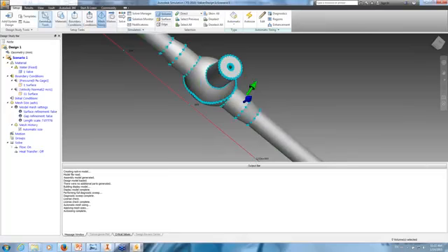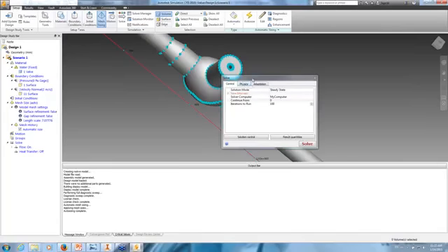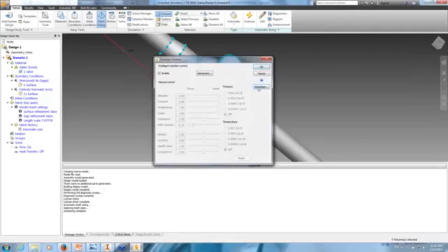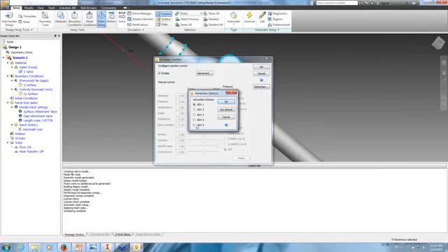So we did the material, the boundary conditions, the mesh, and next I'm going to go to my solve. Under physics, I'm only going to keep this checked. The flow, I'm not going to do heat transfer in this model. It's going to be incompressible, which is the default. That's fine. Under control, I'd like to change the advection to the new advection method that we have, ADV5. That's the one that we recommend that you use. And they might actually change it to the default.